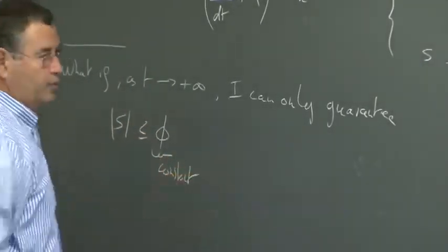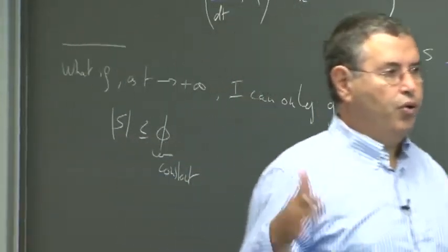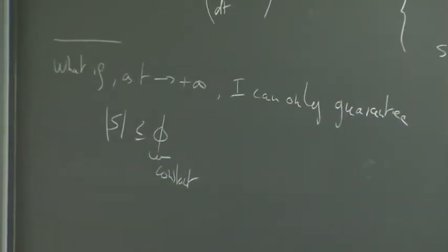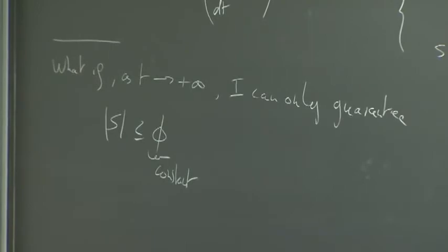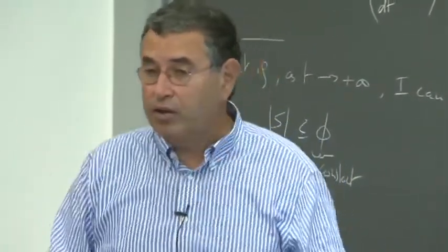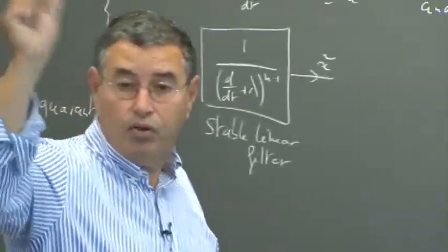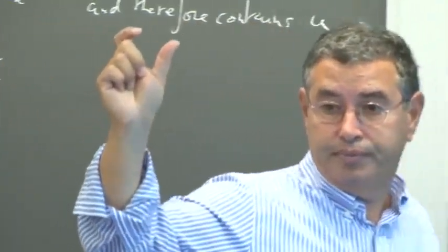In other words, s tending to 0 implies that x tilde tends to 0, so just solve the problem s tends to 0. Now, of course, solving the problem s tends to 0 is itself a control problem, so it may not be solved exactly. Instead of tending to 0, it may tend towards a small region around 0.